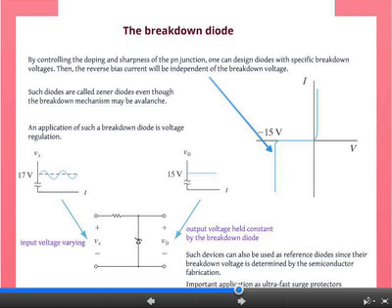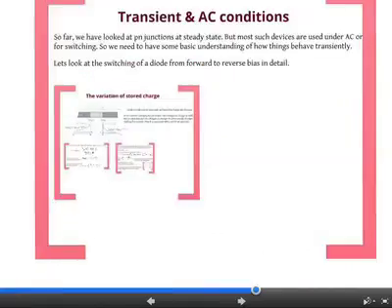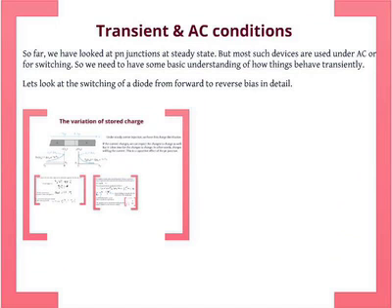Now, the speed of the response is what we will talk about next. So we will look at this in detail because that turns out to be a very important characteristic for the practical application of these devices. Okay? So the speed of the response, of course, is determined by the non-equilibrium situation, right? You have voltage that's applied, and then you switch the voltage to the other side. So what happens for the physics of these semiconductors? We need to understand that because that's what limits the switching speed. Ideally, you want this to be instantaneous, but we know it cannot be instantaneous because charges have to move, okay? And that takes time. That takes diffusion time. We know this, so we expect that, right?